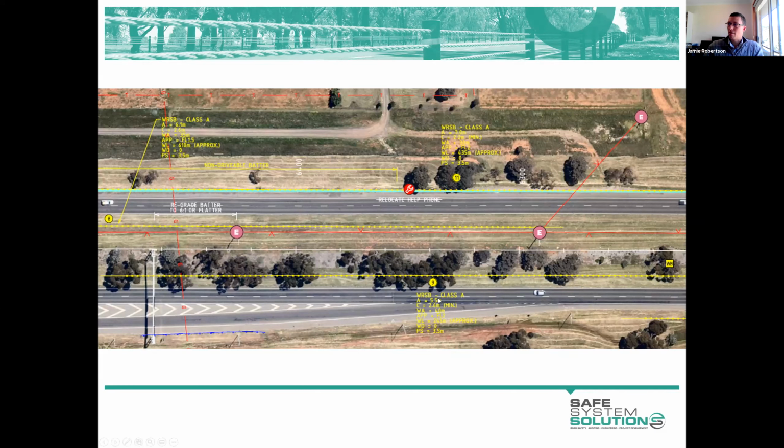So this one here is at 5.5 metres. This one at 6.1. It might be 5.3, 7.2, and so on. Barriers sort of stepping in and out as you drive along that road, and the offsets were based on working backwards from the location of the hazard, locating those barriers as close to the hazard as possible, subject to the deflection of the barrier.